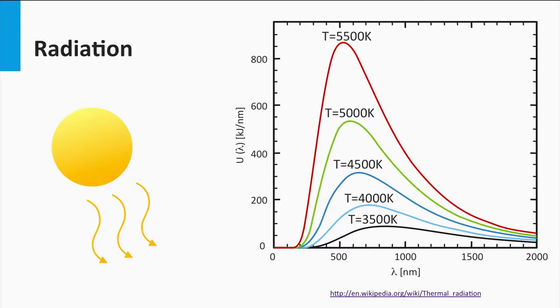As discussed in week 1, a black body is a perfect absorber of radiation, no matter what wavelengths or direction describe the radiation incident on a black body. A black body is also a perfect emitter of thermal radiation. In fact, if a body is a perfect emitter, it must also be a perfect absorber.